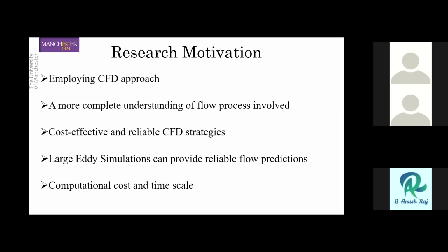To achieve this, we need to identify reliable and cost-effective CFD strategies which can produce reliable and cost-effective simulation of three-dimensional unsteady turbulent flows around wind turbine blades. While large eddy simulations can provide reliable flow predictions provided that the mesh is fine enough, if suitable RANS models can be identified, then the computational costs and the timescales involved will be substantially reduced.